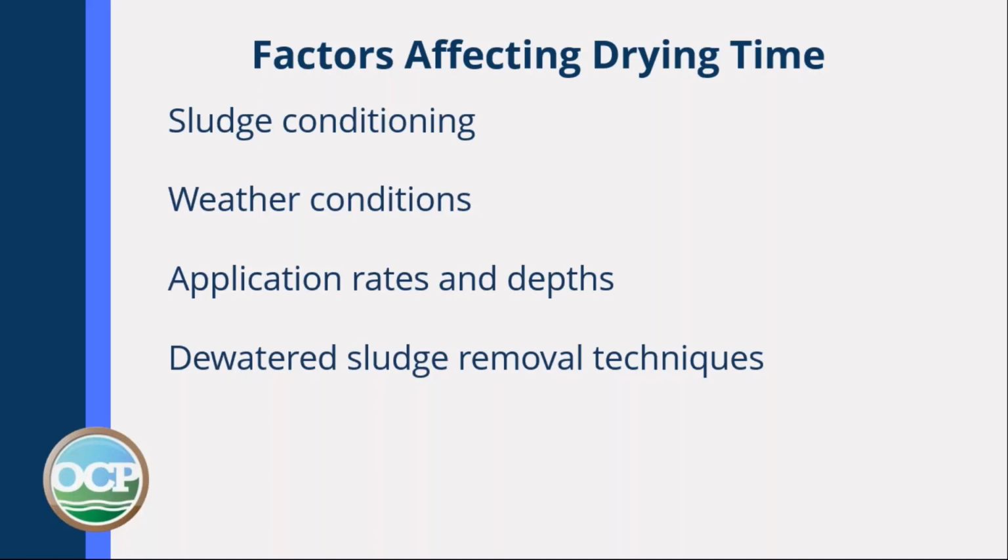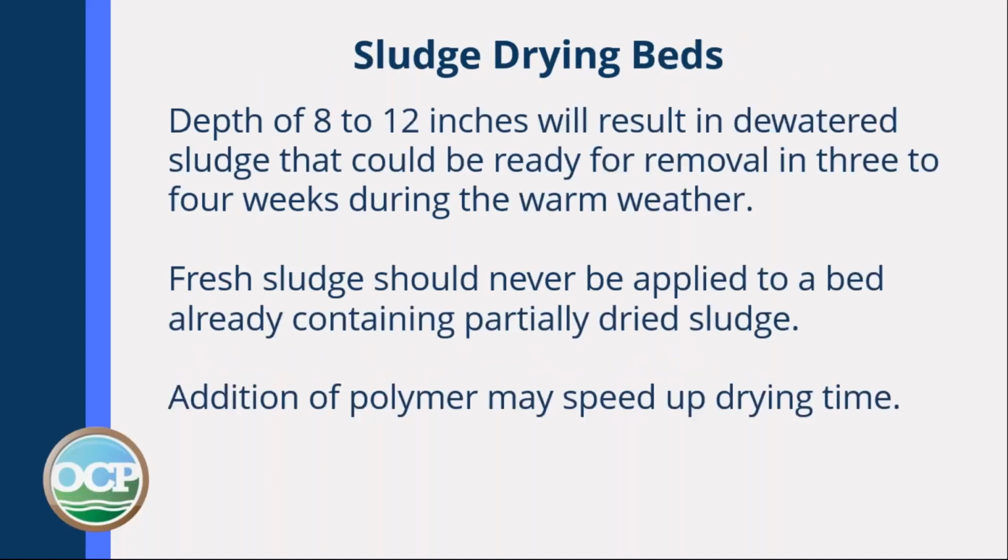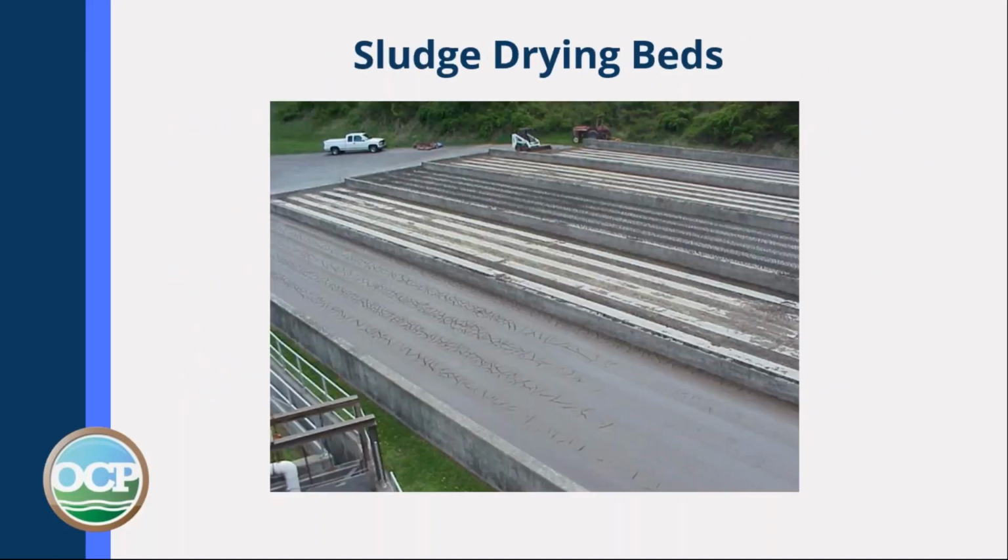It also depends on your application rates and depths in the beds, and how you remove the dewatered sludge from the sand. If you clean it properly, you go right down to your sand bed, then you can lay the sludge right on top of that.